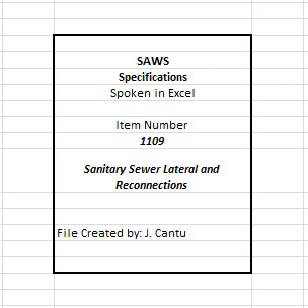B. Employ method and equipment that restore the service connection capacity to not less than 90% of original capacity. C. Immediately open any missed lateral connections and repair any holes drilled in error using a method approved by the inspector. 5. Reconnection on parallel or replacement segments.